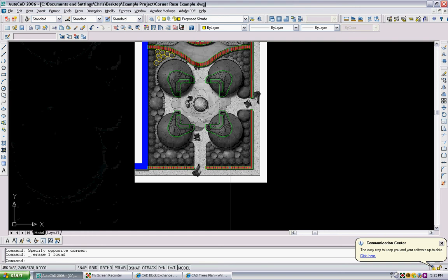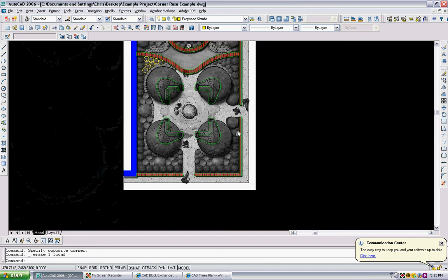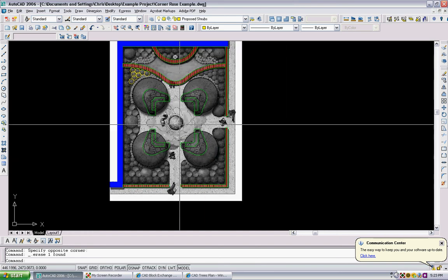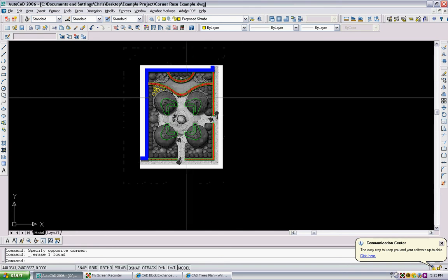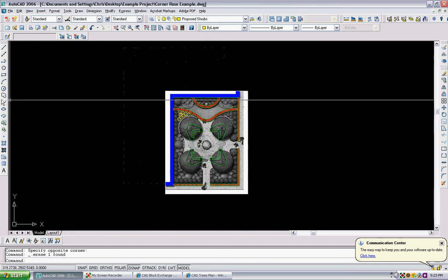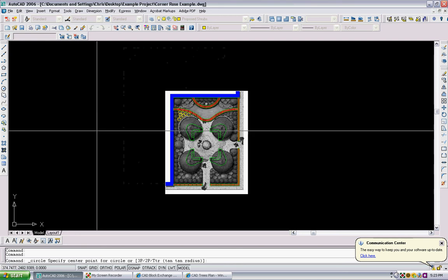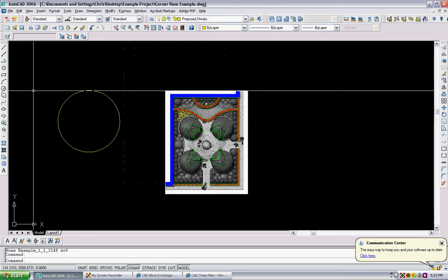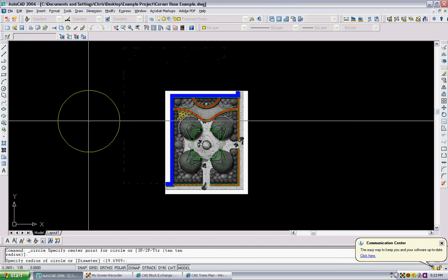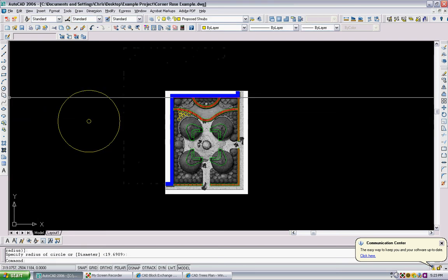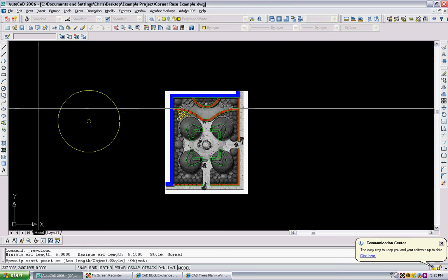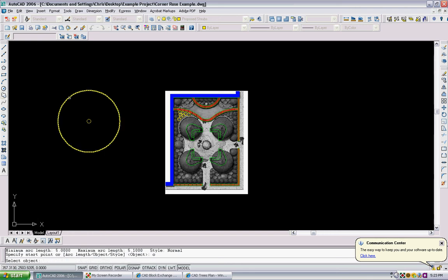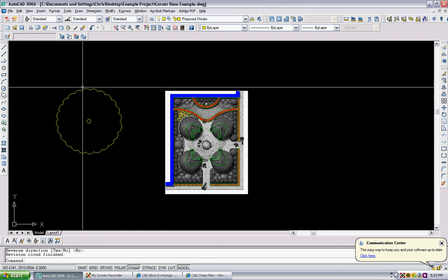And you would set them to your appropriate layer, and get the line weights according to the line weights you're using for your pen settings, and so on and so forth. And that's basically how you bring in blocks from the internet. If you wanted to make a block, say you wanted to make a tree. Okay, so I'm going to have this here and grab the midpoint of it. Now the Revision Cloud tool also allows you to make an object, a polyline, into the Revision Cloud. Type in O for object, enter, click on it, enter again, there you go.